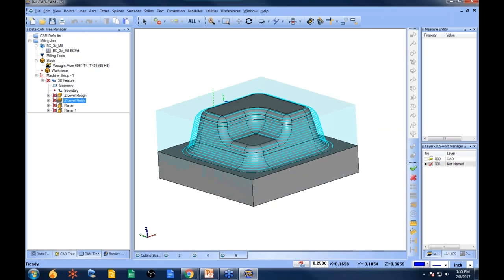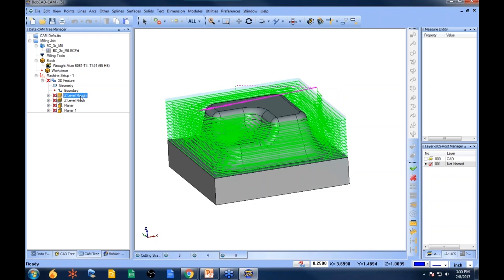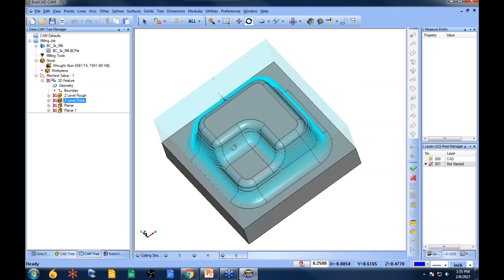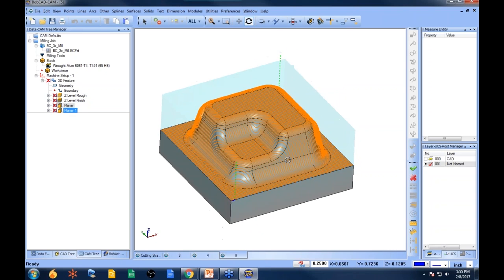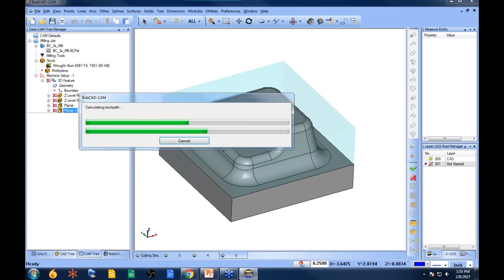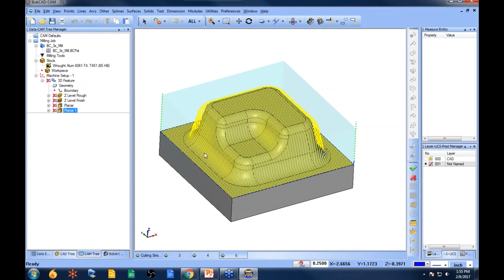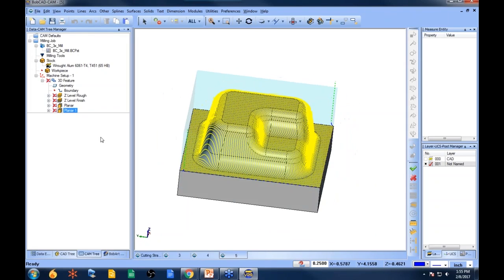All right, so moving forward. Okay, so we got our Z-level rough to rough this out. We got our Z-level finish. This is getting more of the vertical walls. Again, it shows how the flat areas of this part are really not applied, and then we have our planar to go back and forth, and we can do our planar in the other direction to go back and forth. So using these very common strategies, you're able to clean up these areas of the part.